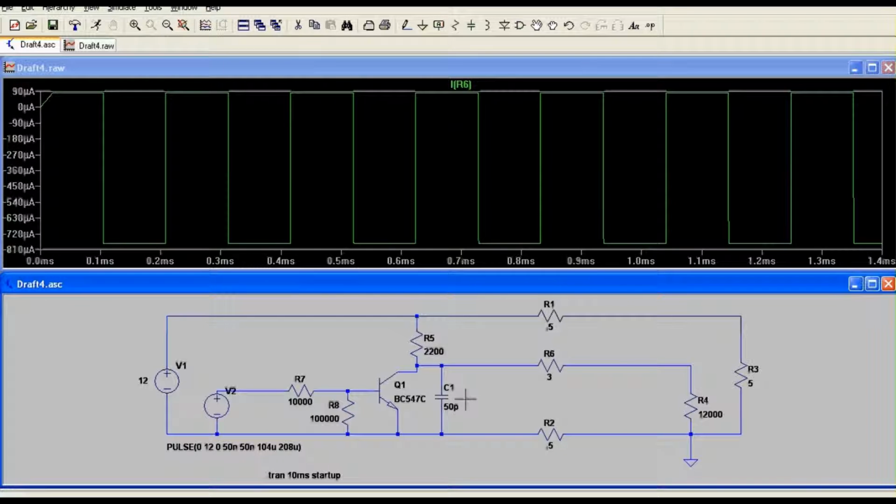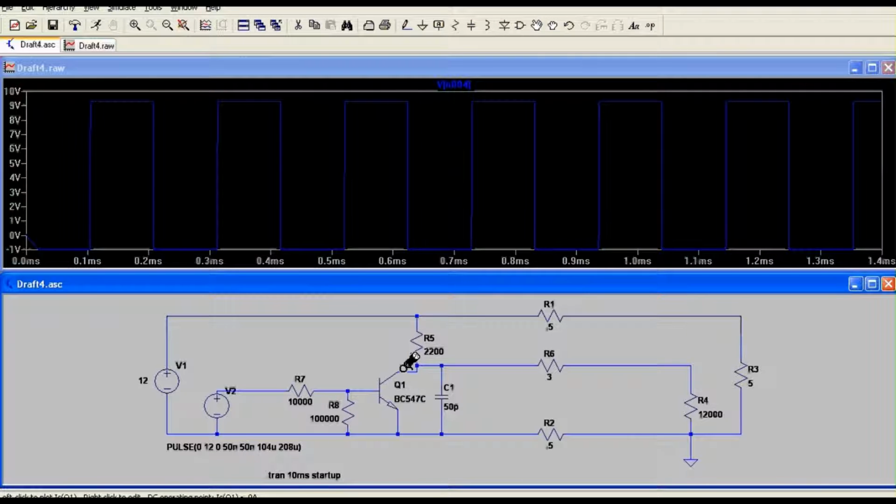and in fact, just to really try to illustrate that, I might get rid of a couple of components here. Just bring it back onto that. So I'm just going to get rid of that 2K2, and I'll get rid of the 50 picofarad. And I'll just get rid of that there. Remember, I'm saying, let's imagine that transistor is on, and I'm saying that because we're saturating, there's really not a lot of resistance there to really consider. And there's only 3 ohms. I might leave that there, but you can start to think that it's like 0 ohms.